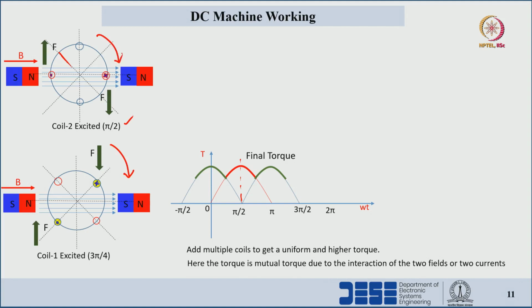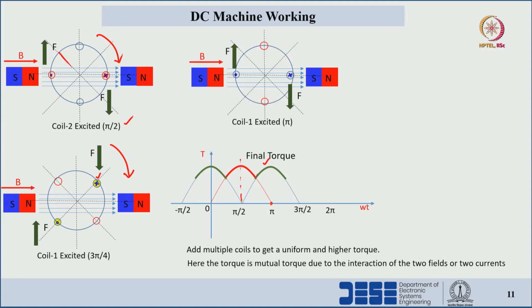The rotor has to rotate in a clockwise direction, right. So we are changing the coil 1 current, which we can see highlighted with yellow color. The coil 1 current is reversed such that again we see positive torque here, that is the green color one. At an angle of pi, the coil 1 will reach this point, and again it will see the maximum torque. Here the interaction between the current carrying conductor and the magnetic field lines is high, and for that reason high torque is happening. With respect to the magnetic poles, attractions and repulsions, we can see this side north pole and this side south pole. So these two poles will repel each other and the rotor will try to move in the same clockwise direction only.